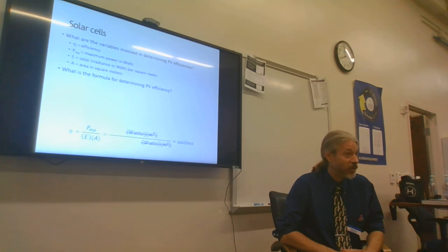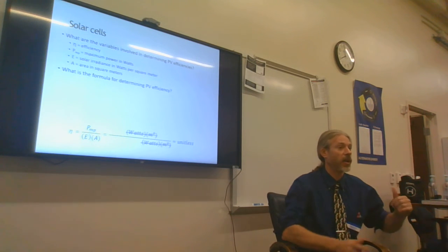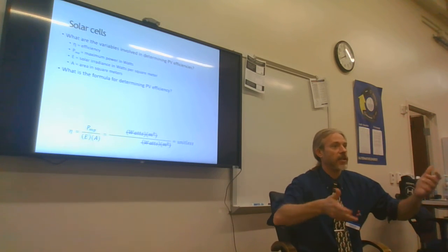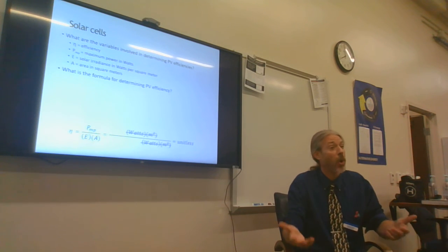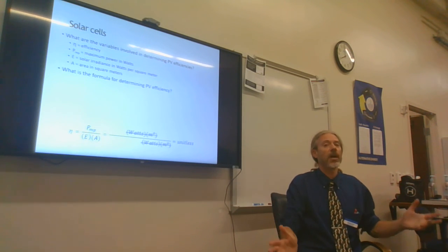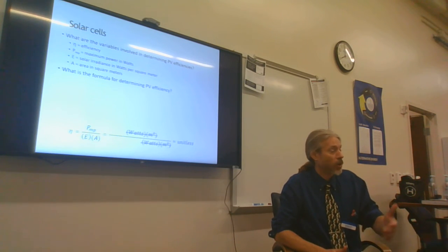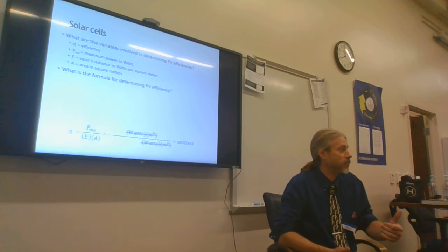The slow way to do it is you look at the dimensions of your panels and you try to be like, well, I could fit this one up here in this way and this one up here in this way. Oh, well, we have all this extra space. Why? Because these panels don't fit easily into the dimensions that you have on the roof. You just want to start with a quick maximum. Sir or ma'am, you're only going to be able to fit about 2,200 watts of solar panels on your roof at the absolute most, but you need a 5,000 watt system. So would you rather have a large electric bill still and have a roof mounted system, or do you want us to design a more efficient energy wise but ground mounted system for you?